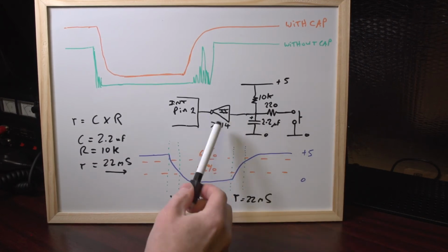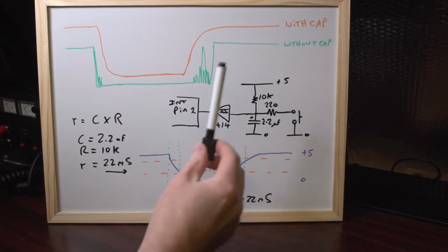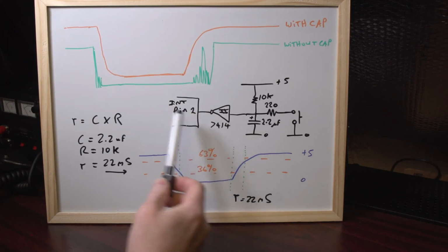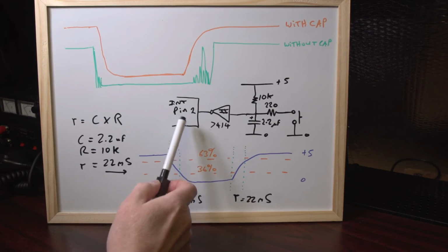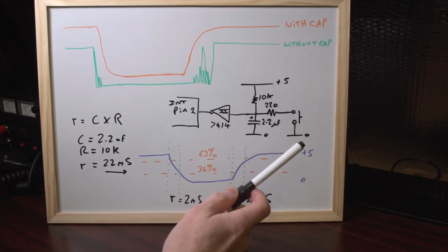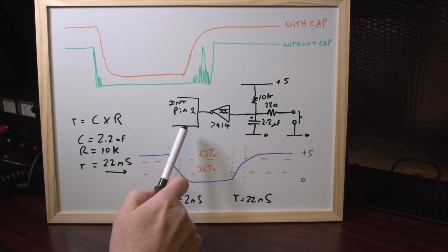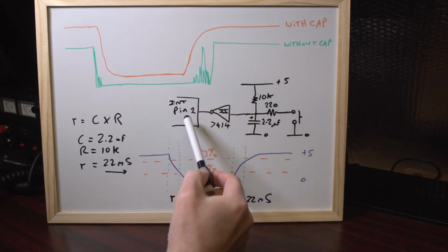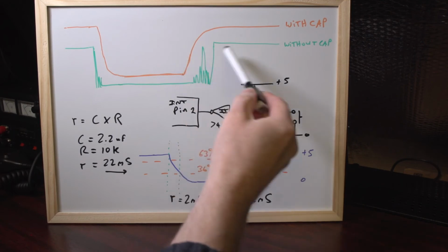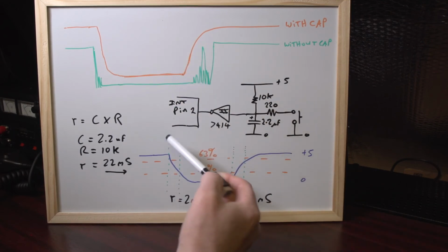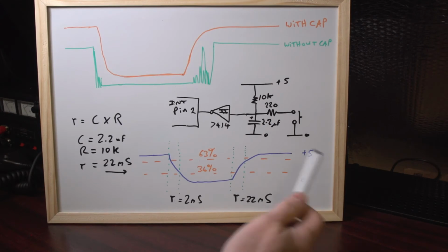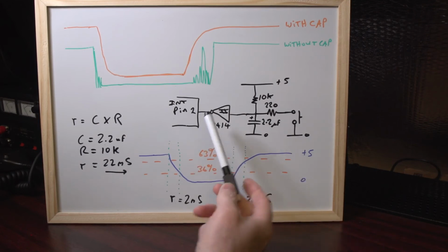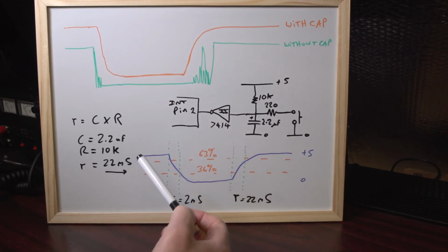If you make it faster than that, like using a 7414, which gives you nanoseconds per volt, it's incredibly quick, then you have no problem whatsoever. But if it's too slow, you actually get multiple activations of the interrupt pin. I had to spend some time figuring this out because it's not documented. I didn't understand why, when you disconnect the Schmitt trigger, the rise should be clean enough to give only a single interrupt. When it passes the detect point, it should just activate, but it wasn't. I was getting about 14 or 15 activations of the ISR code every time the button was released or pressed. So that's potentially something brand new, and we'll see what people think about it.